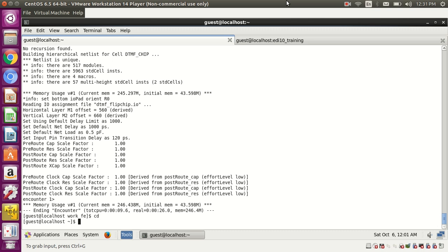Net is different. Net means all the shapes we have, everything is net, but the shape will be there, that M1 shape. So whenever we have any parallel shapes with the clock nets or with some other high power nets, so that's how it will calculate. It will add extra load on that, and extra load on this. So the tool can drive both the nets, our design can drive both the nets. That's how they calculate the SI, so that they can withstand the SI effects that can happen. I think you got my point.